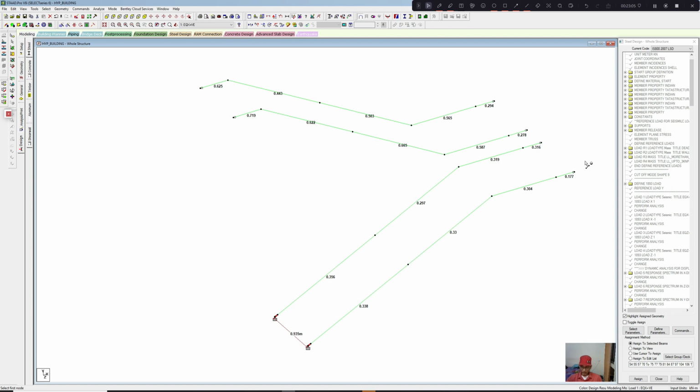As I have told, while detailing this part where we have released the effects, we should provide slotted holes so that there is scope of movement of this stringer when a seismic load or lateral loads occur.